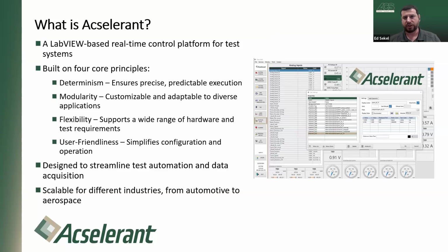So if we need to, as Roy said, have EtherCAT I/O or DAQmx I/O, or if we need to have Modbus or EtherNet/IP, we can add those modules into the system and then configure that I/O and route it to a main, what we typically call machine module, where we would define the overall process of what the system is going to do. So that's where we would determine how it's meant to operate and what functions are configured for the system.